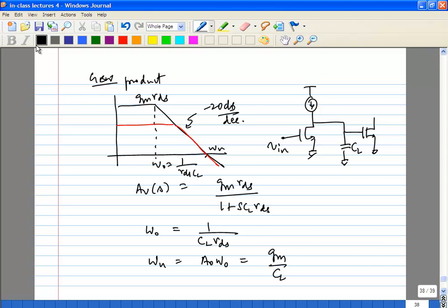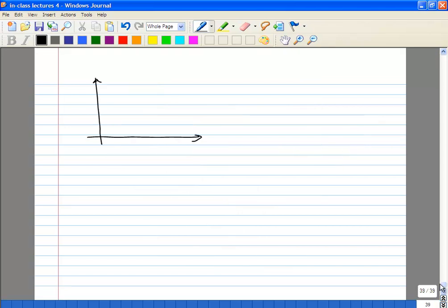One thing you can do is, of course, increase power dissipation. But suppose you do that. Suppose you just increase the current in the amplifier. What happens? If you plot your GM versus I naught, of course it increases, but eventually it does saturate because you're starting to go into short channel. Remember velocity saturation. So eventually your GM is going to saturate as a function of current. So you really don't gain that much.